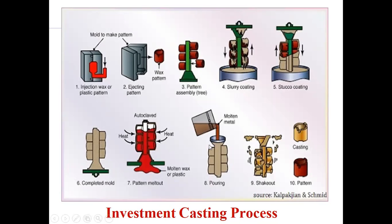And all that is remaining is your shell, right? This coating, the slurry coating which was there, that will remain once you have applied some heat. If you have given some heat, the inside wax will melt out, and the outside profile because of that slurry coating will remain, and you will fill molten metal in it.